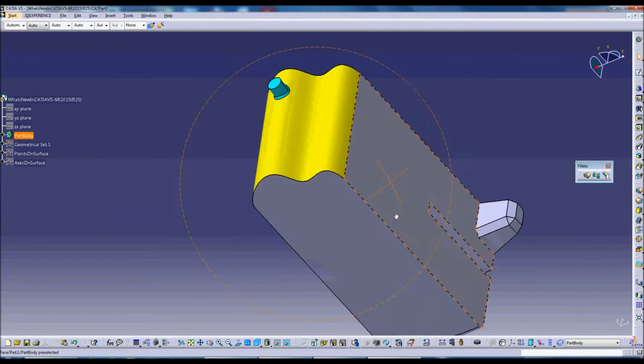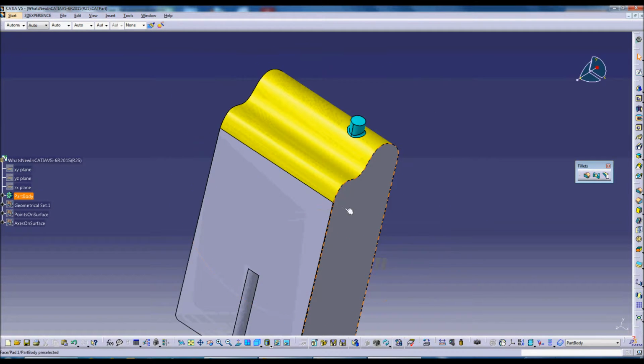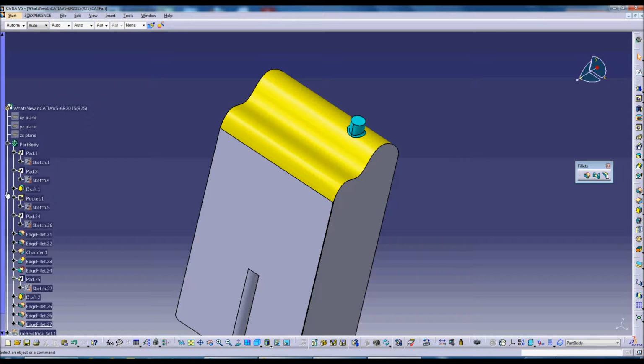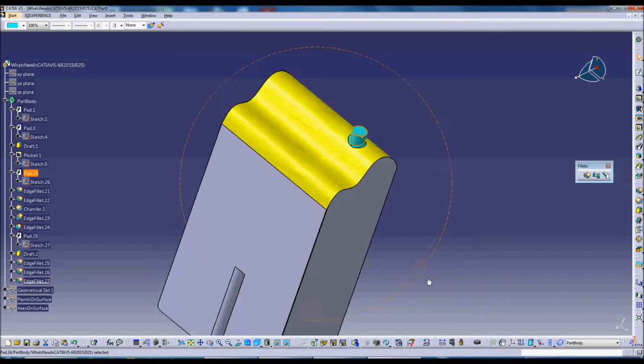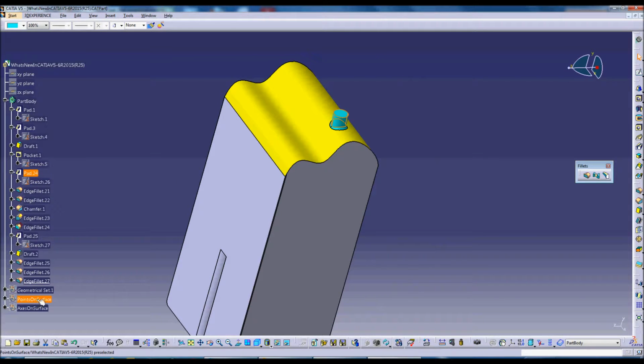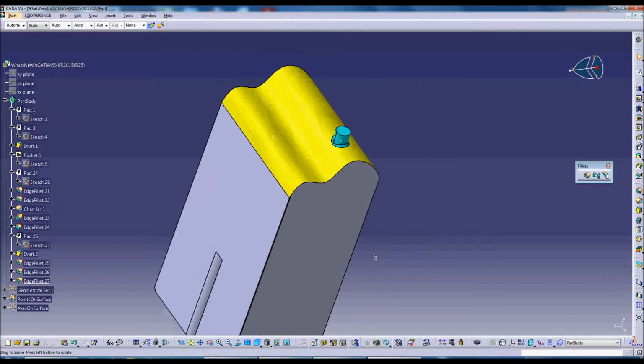3D pattern. So the user pattern's now been enhanced so that it's not just a planar sketch full of points, which still works exactly the same, but we can have a geometrical set of points in 3D. Same user pattern function. So select the feature we want to pattern.